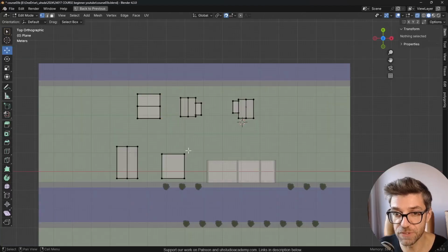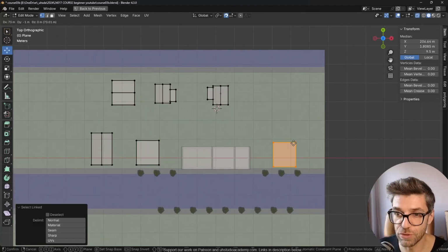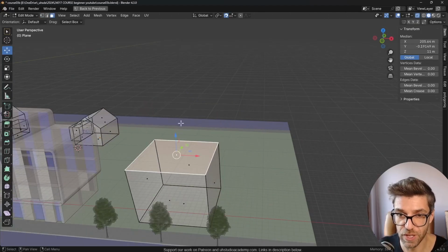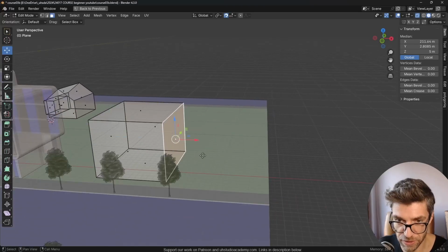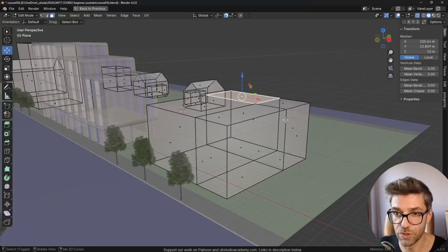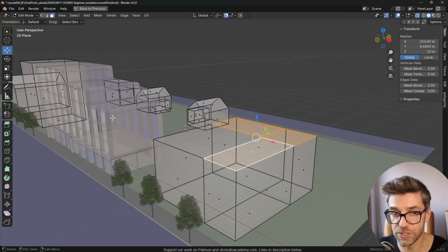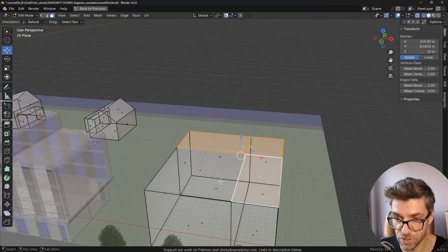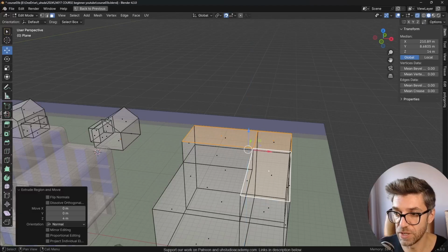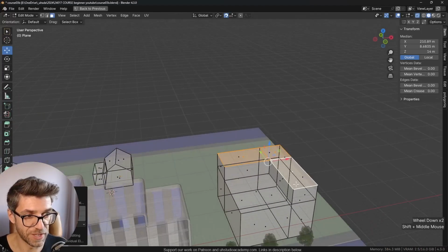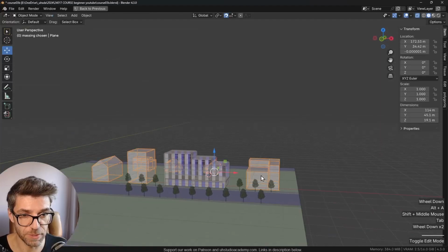And I'm going to do it even quicker now. So Shift D to duplicate this. It will help you see the kind of speed that you can also work with when you are working with Blender, and you get to find your way around it a bit more. And notice also I'm using more hotkeys than the toolbar, but everything I'm doing here, which is basically extrude, and G, which is for move, is found here. And remember, you can see what I'm doing exactly in this corner, unless I'm covering it, which I'm usually not, but this time I was.